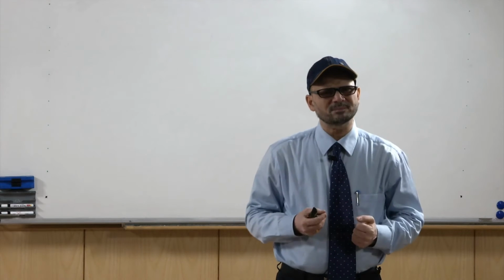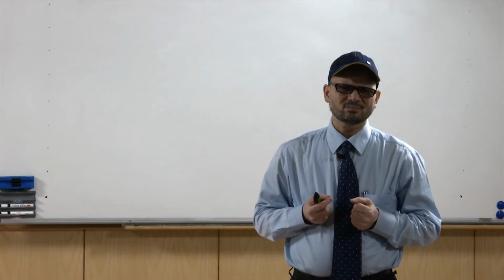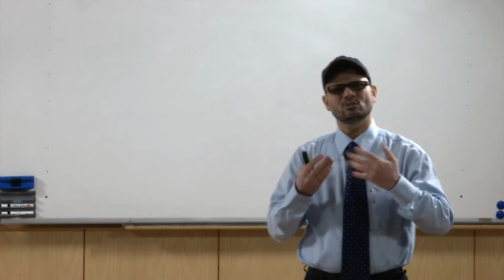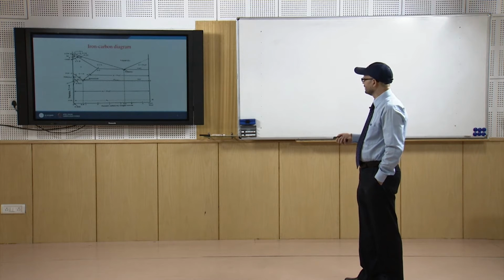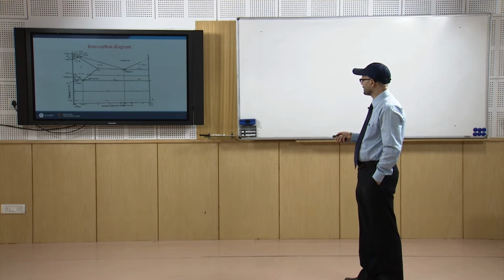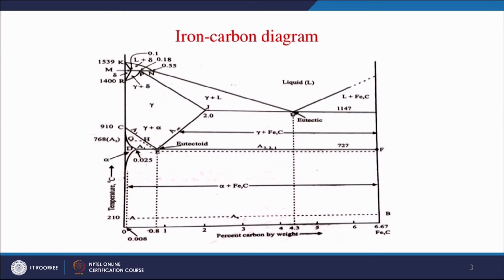This way, at the end you have a different kind of structure which gives you different kinds of properties, because all the phases have different properties. Like ferrite, which is extremely soft but not stable at room temperature. In this zone you have the cementite, and austenite which is FCC. This has good deforming properties. Being FCC, you can deform in this range and it has good plasticity. And cementite, if it is more, is extremely hard and brittle.